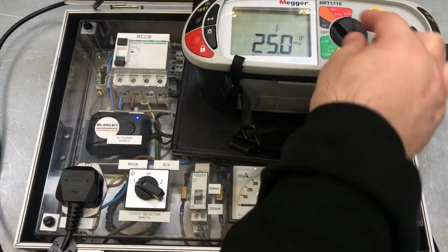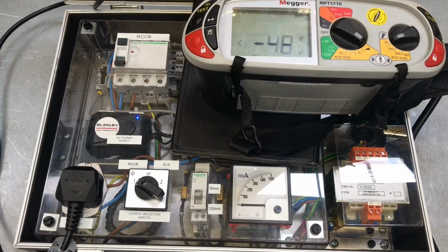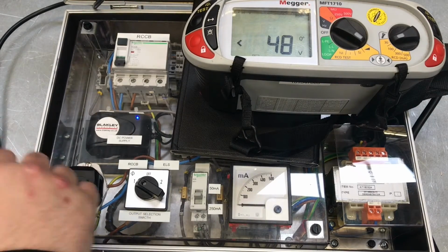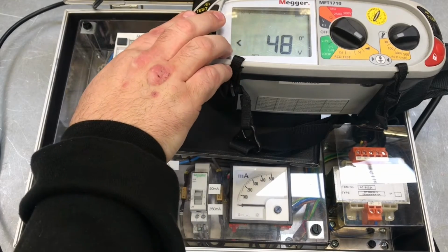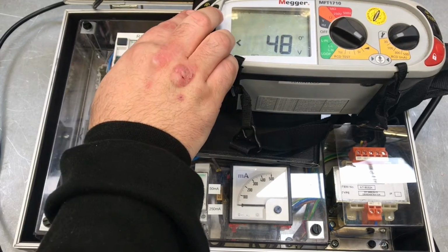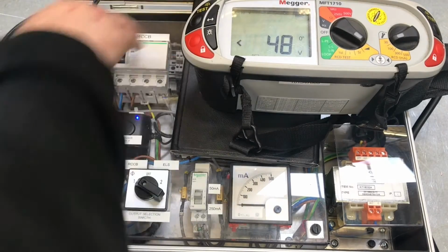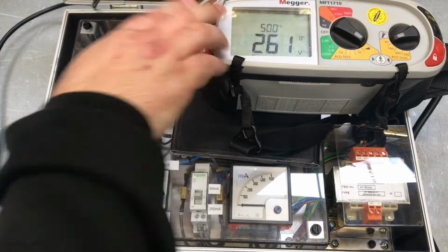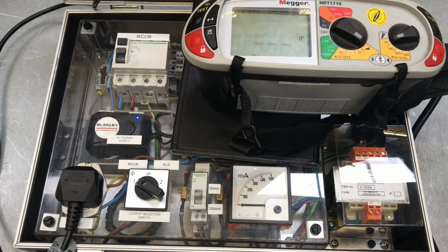Now, the one recommendation I always say to sparks, before you leave a new installation, do a ramp test. You want to know how sensitive that RCD is, because the last thing you want is the next day you've got a 3-day job booked and you're being called back. So I always recommend you do a ramp test to see how sensitive the device that the wholesalers have provided is. And this one, 25 milliamps. I have occasionally found devices that have been 16, 17, 18, and with time and wear, these will also change the characteristics of the device.